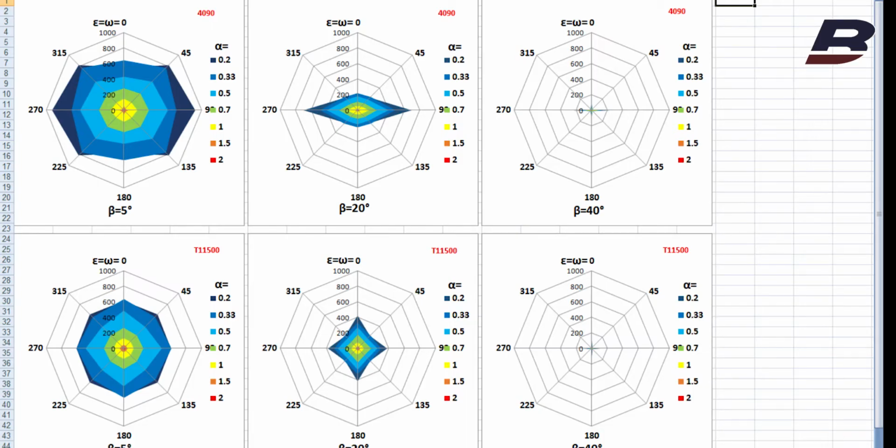We can clearly see that no matter if it's 0 or 90 degrees orientation for OmniCube Avery Dennison, you will get the same performance. For 3M, you will see the difference between 0 degrees and 90 degrees orientation of sheeting at angles wider than 15 degrees.